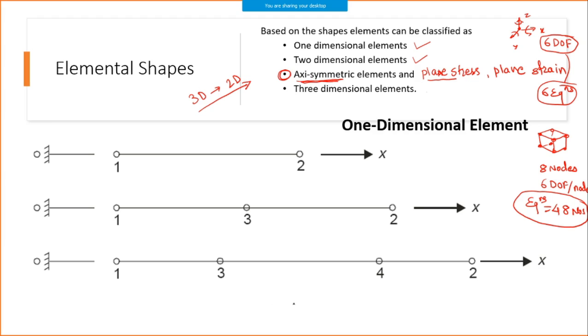One concept is axisymmetry. Consider an element with axial symmetry, and instead of doing an entire complicated analysis, you can reduce it to maybe 3 or 4 elements, and it will reduce the number of equations. That is the advantage we can get. In a similar fashion, you can get an advantage in the plane stress condition and the plane strain condition. If you want to analyze an entire model in all three directions, then 3D analysis is the obvious case, and we can go ahead with that.